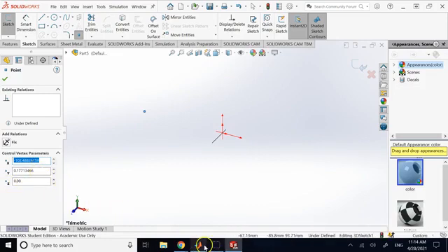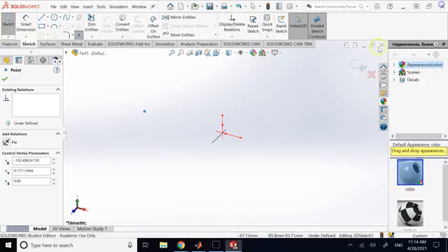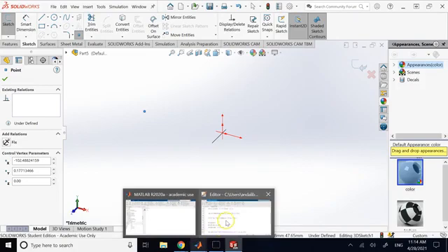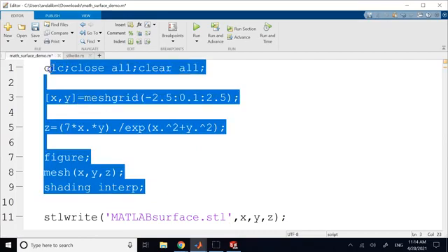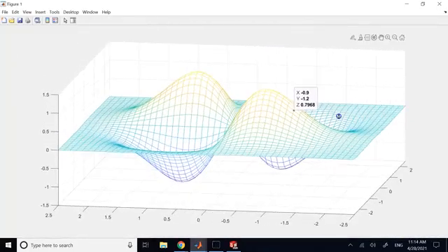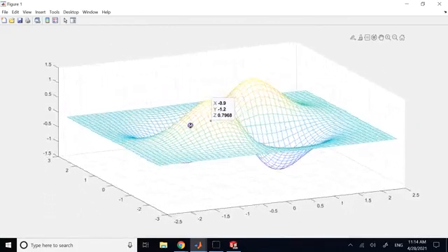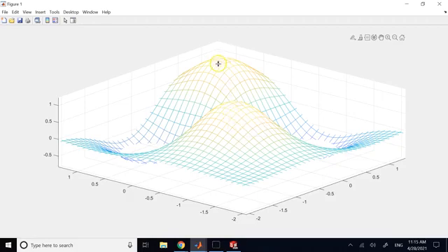And then the most important thing is the tessellation, right? So in order to show you here, what you need for a 3D printer is a mesh file, correct? So let me reduce the resolution here, and I show you that when you create a mesh file, what you have basically is the digitized surface, right? You cannot have infinitely many points. You only can have a finite number of points. And here you see all of these points that are connected together.